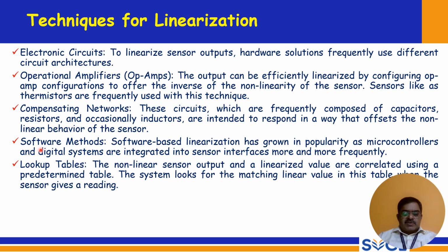So there are software methods also. Software based linearization has grown in popularity as microcontrollers and digital systems are integrated into sensor interfaces more and more frequently. So there are lookup tables also. The nonlinear sensor output and a linearized value are correlated using a predetermined table. This system looks for the matching linear value in this table when the sensor gives a reading. So these are a few techniques, and also